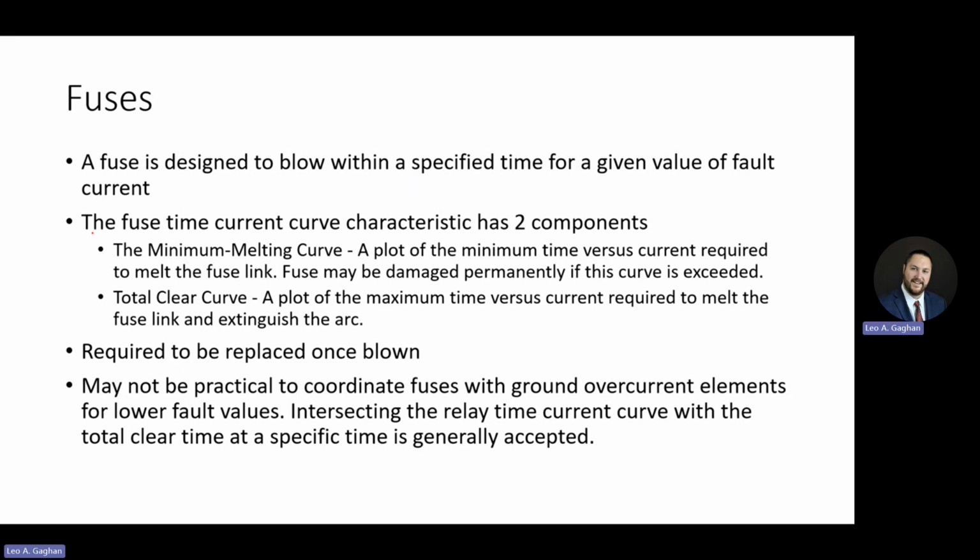The biggest downside to a fuse is they need to be replaced, right? Once a fuse is blown, we don't have any technology to tell us where it was blown, when, how. You have to send a technician out to find it. And then once he finds it, he needs to replace it.